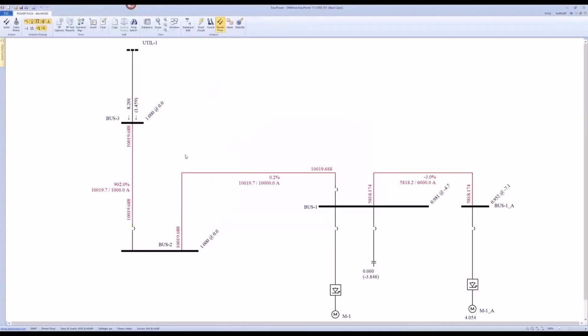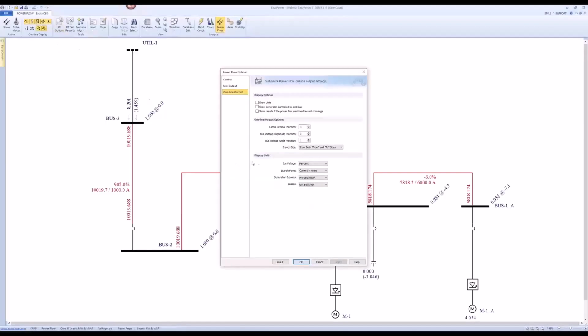kVA demand, very simple as well. Again, my example is very simple, but for your power plant or your plant, it's not always simple because the load flow does not always give you the kVA demand. You have to think about what's your worst case largest load demand in your system throughout the year. That's what you need to enter over there, right?